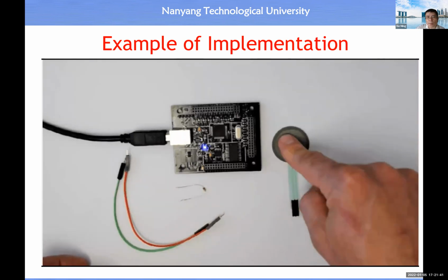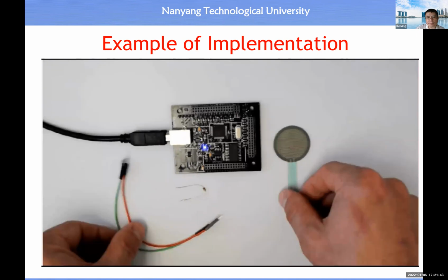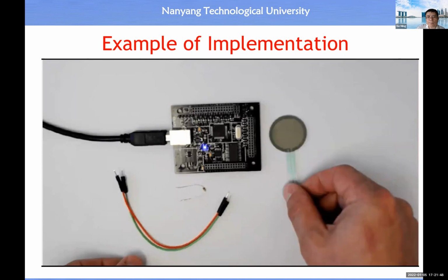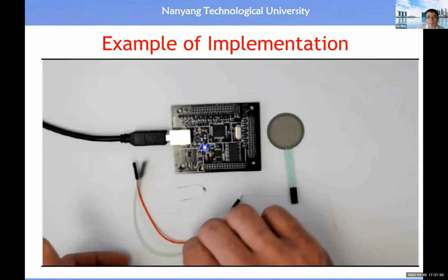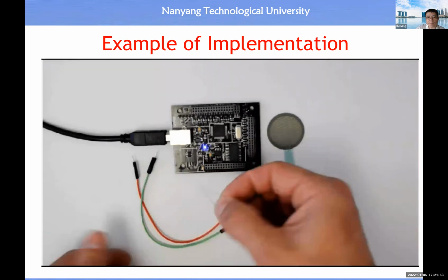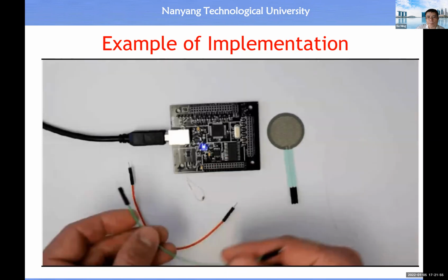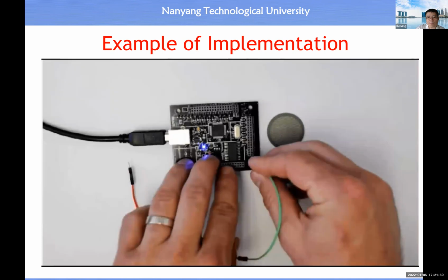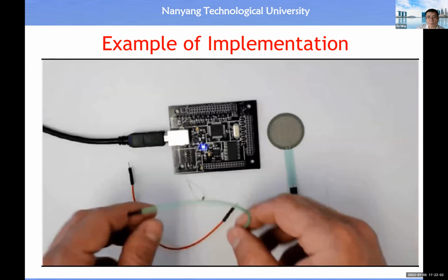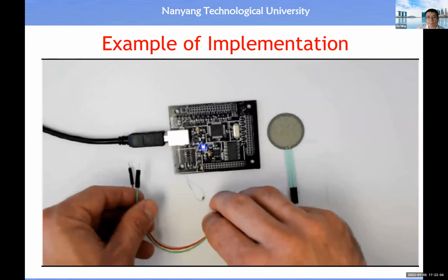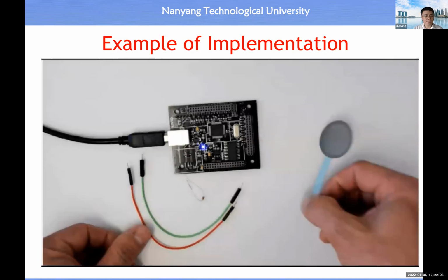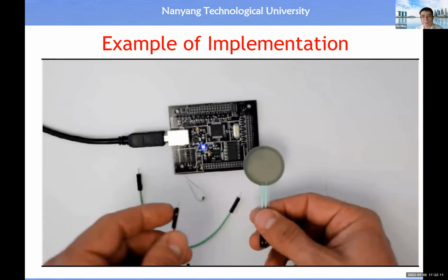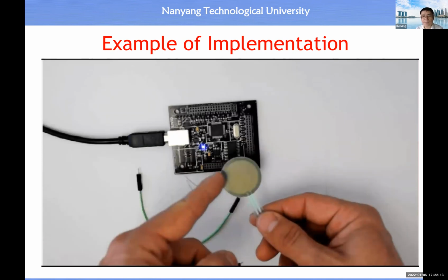For this example, all I need is a Brain Junior, an FSR pad, 2 jumper wires, and a 10K ohm resistor. The nice thing about the Brain Junior is we designed it to work with these cables that can easily be plugged and unplugged, so you can do completely solderless connections. All right, to get started, I need to take my FSR and plug it into the brain. I'm going to be using analog connections here since it sends out an analog signal.